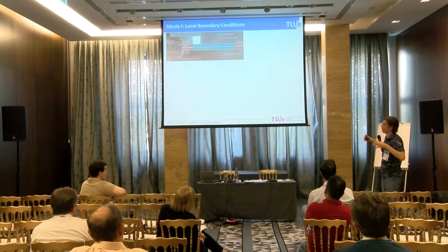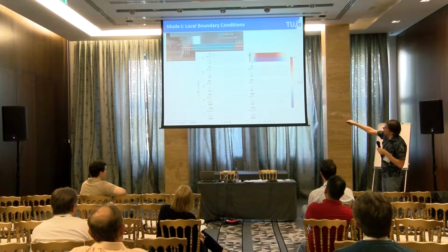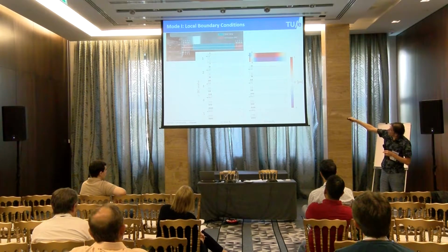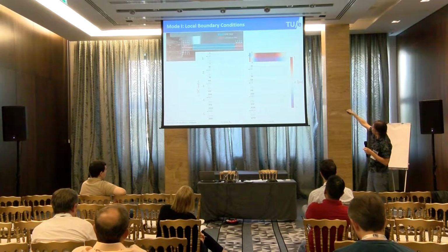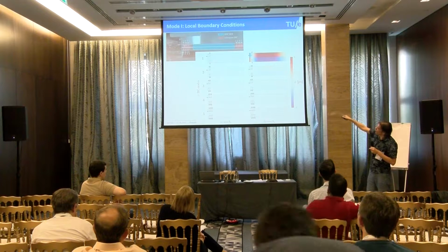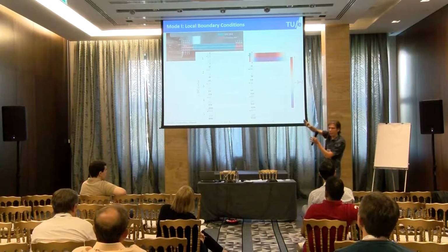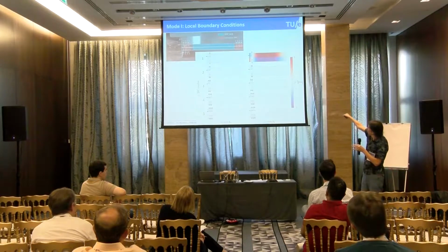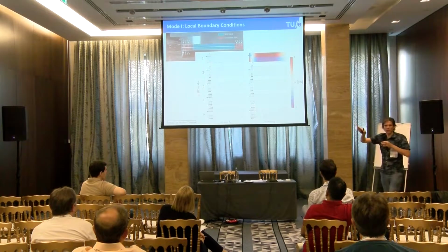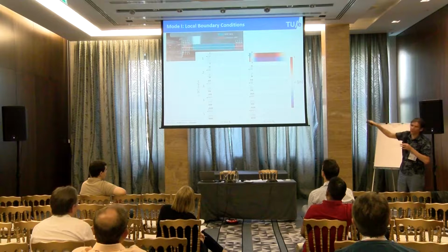So we approached this from another direction and said, okay, how many nodes do we actually need? If you have a double clamped beam, you could say, I just take 2 points and start pulling on it. Then we get a big error in the displacement field, which is what is shown here. With 2 of them you enforce the right angle, and it becomes better. It's almost 0, but you can see there's still something. With 3 of them we also put in the curvature, and it becomes better. With 4 of them, you also put in how the curvature changes with position. That should be enough to describe this specific test.